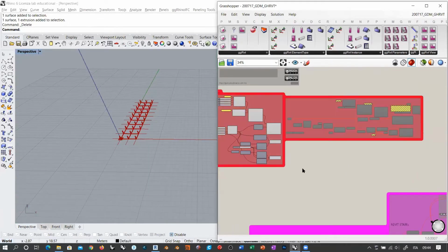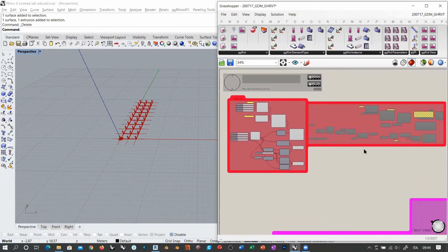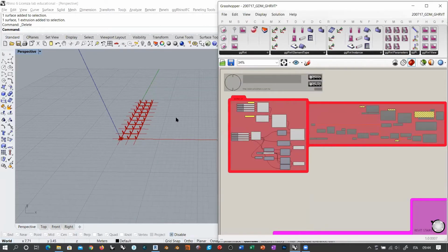There is the IFC export, and of course this is pretty obvious, but as everything here is based on IFC, the encoding of the IFC properties depends on the Rhino document units. I do recommend that you pay attention to this thing here.